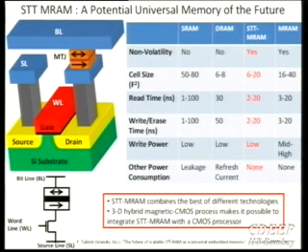So the interesting thing to note is that if I were to use a structure which looks somewhat like this on the left, which is an equivalent circuit, I have this magnetic tunnel junction, and this is the hard magnet, right? And this is a soft one. I can change it by writing a proper current either from the top or from the bottom. Writing turns out to be a little bit different than reading. I have to figure out whether to have current from the bottom or the top. And if I do have a structure like this, by sensing whether it's a high resistance or a low resistance, then I can actually have a memory, right? So this looks like a memory structure.